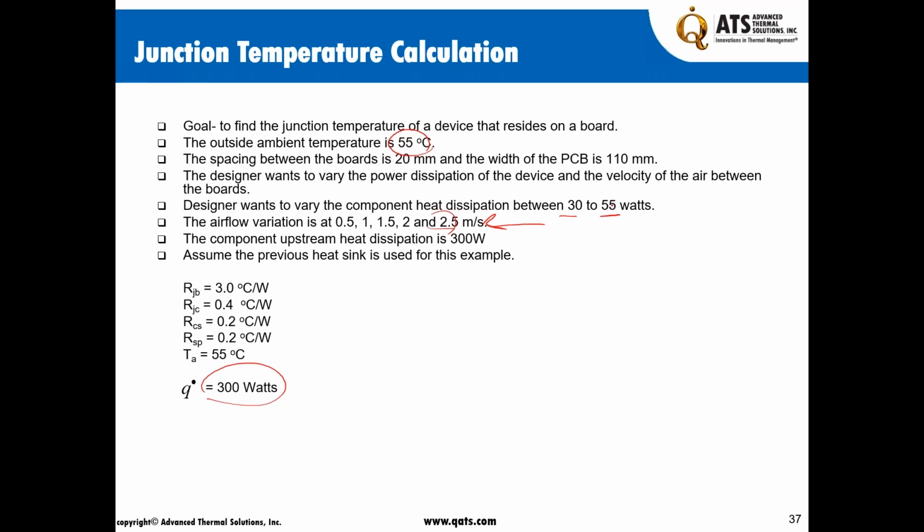But the question is upon you as a thermal engineer or a system engineer to ask that question: can the system see the maximum power? What if I have 100% traffic at one point on this system? Can the device shoot up to 55 watts? And if it does, the system has to survive. We've had examples in the past. You may remember in Super Bowls and so forth, when they show a commercial, everybody goes and logs into a site, and the systems crash due to the traffic, and oftentimes it's due to a thermal problem because the system is at its most elevated power demand and it cannot cool itself off, so it shuts down.